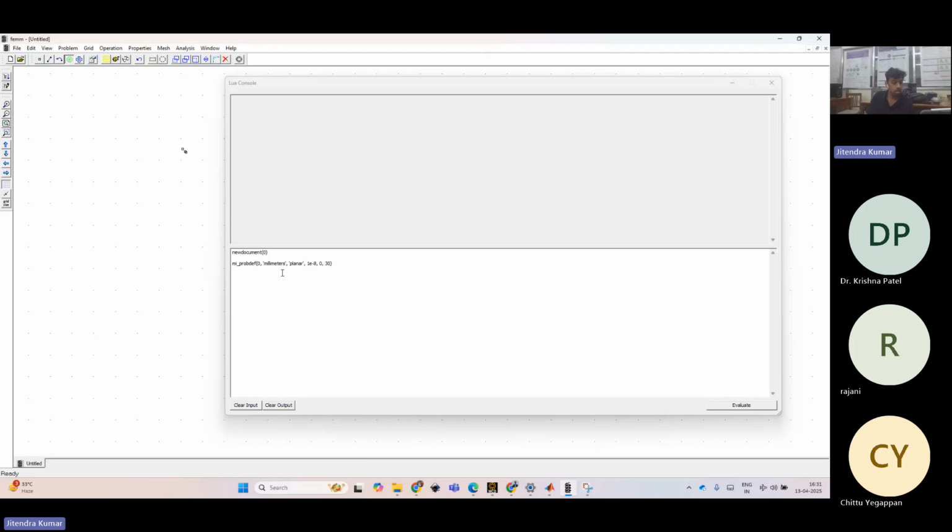Apart from that, how much accuracy do you want? If you increase this accuracy, points like places or gaps between the meshes, that is the unit here. And this is for 2D. If you are inserting zero only, that defines 2D. And this 30 degrees is nothing but the angle between the different meshes. So this much initialization you have to do.